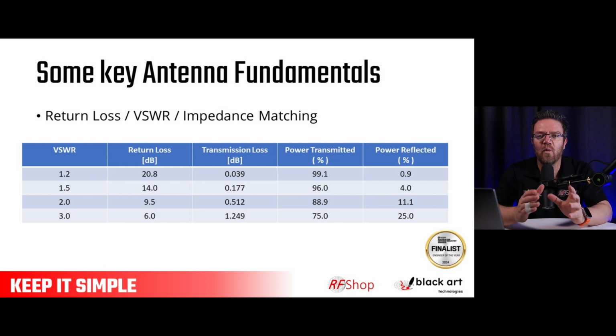So meaning how well does your circuit then flow into the antenna, and if they are the same value, that flow from one to the other, the impedance on this one and the impedance on that one is very similar, and it just flows through. It's really like water flowing. It's the same logic, it's the same principle. But if there's a big mismatch, this is my system coming in, this is small, this is much bigger, there's going to be discontinuity between the two, and that discontinuity can give you a lot of problems, which is what I show on the slide here.